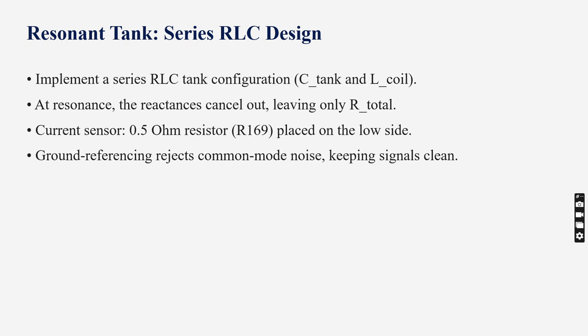We designed the resonant tank in an RLC configuration. In series resonance, the circuit impedance drops to a minimum, equal to the total series resistance, allowing maximum current to flow.